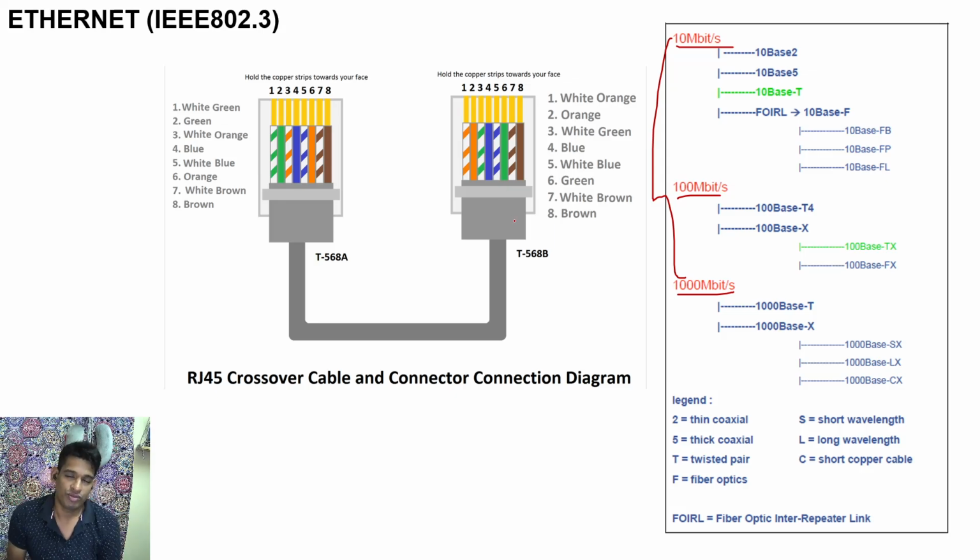So in your substation, when you are crimping an RJ45 connector, or connecting your relay to a network switch, you might be thinking that this is an Ethernet LAN connection. But what you have to take from this is that Ethernet is not a simple protocol, it's a collection of various data link and physical link protocols.